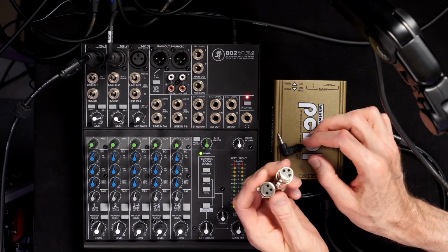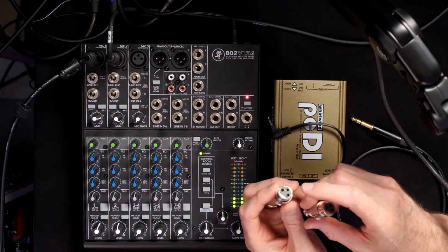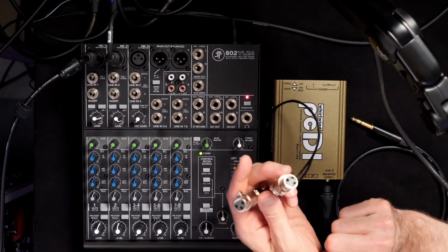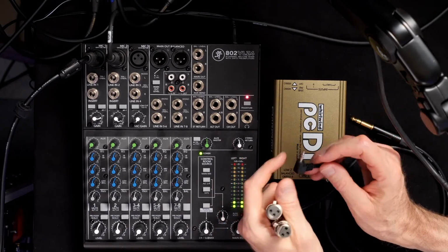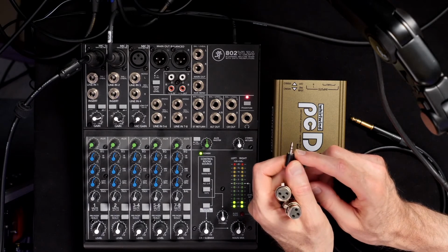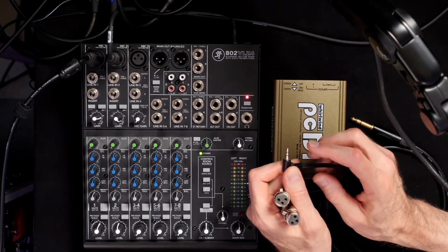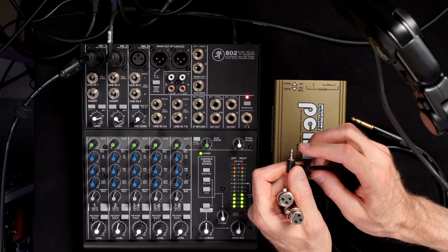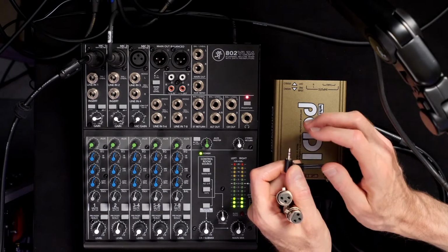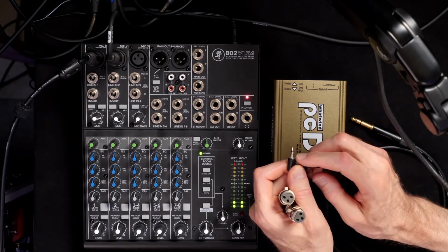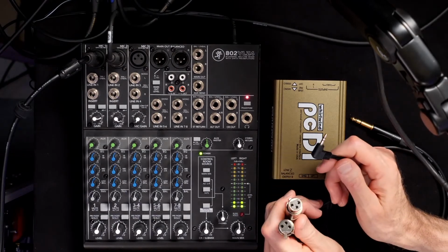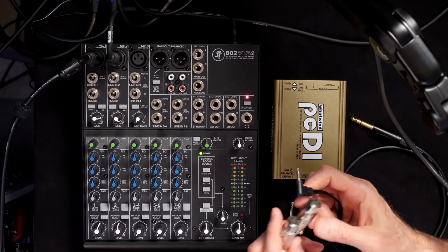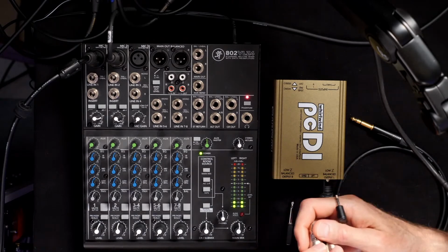And what it's supposed to do is take a balanced signal here and a balanced signal here and just take the first audio line from each of those and send them to an unbalanced connector here, where you have audio from the left channel on one, audio from the right channel on the other, and then ground on the third one. So balanced to unbalanced. But in fact, it doesn't do that. It's wired incorrectly. So that's why we had that issue a couple of weeks ago.